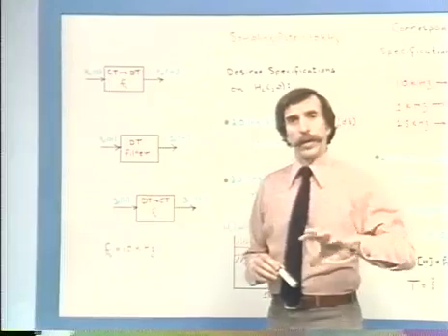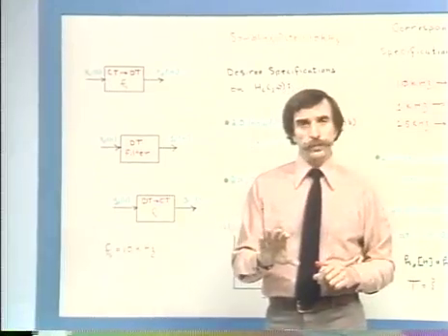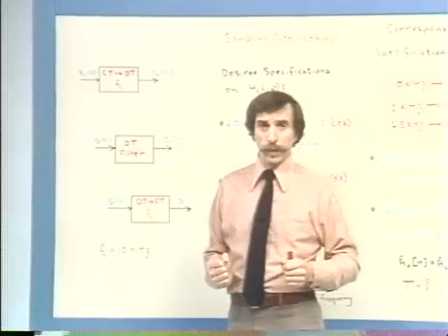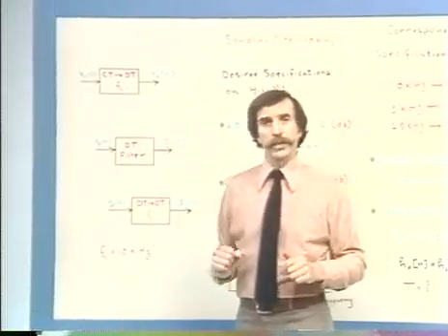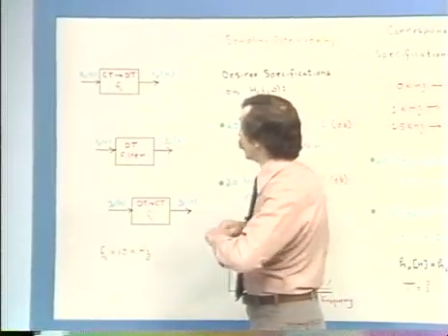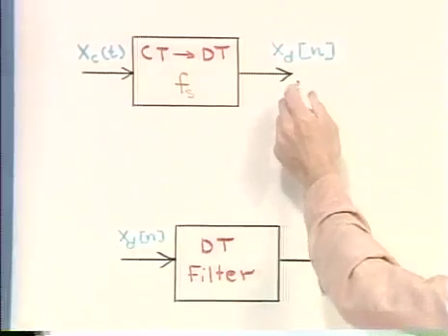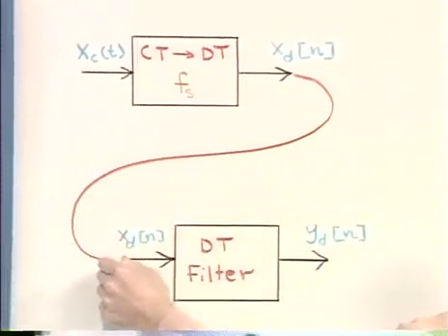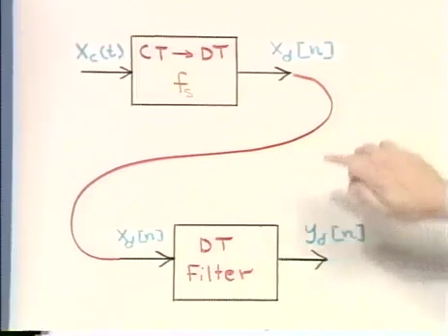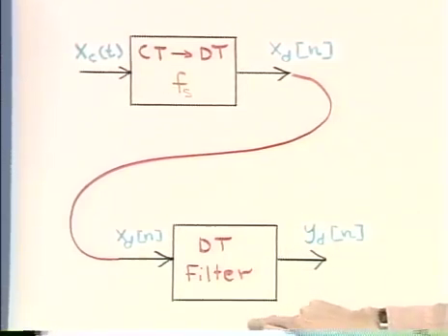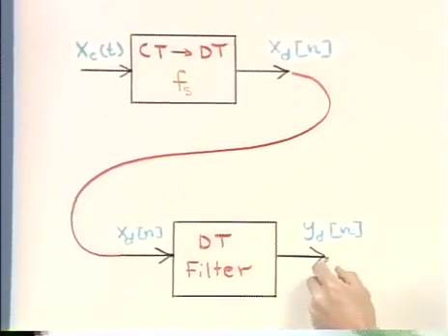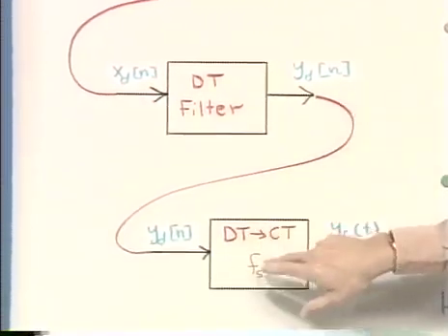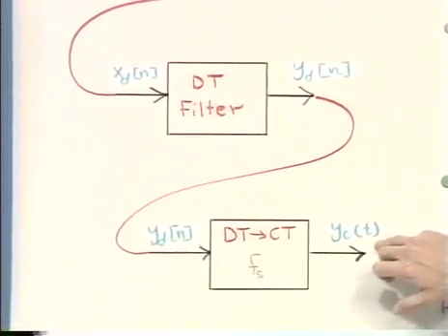So we're talking about now a discrete time filter that we want to design through impulse invariance from continuous time Butterworth filters, and we're going to get our design specifications in the context of having considered discrete time processing of continuous time signals, where we will map from a continuous time signal to a sequence, carry out the filtering with the discrete time filter that we're going to design, and then we will take the resulting filtered output and map it back to the continuous time signal.